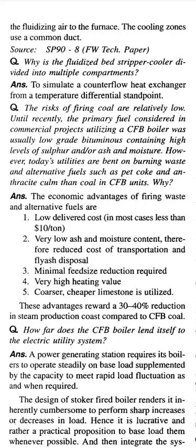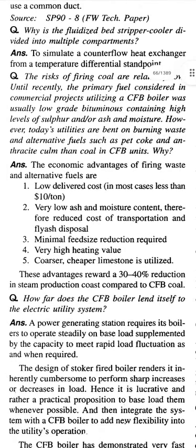However, today's utilities are bent on burning waste and alternative fuels such as petcoke and anthracite culm rather than coal in CFB units. Why? Answer: the economic advantage of firing waste and alternative fuels is low delivered cost, in most cases less than $10 per ton.